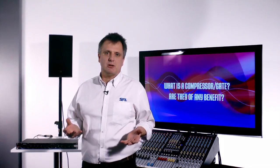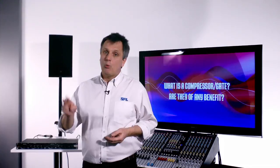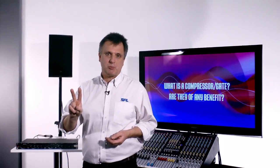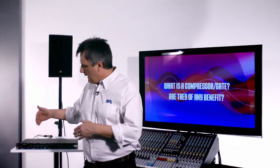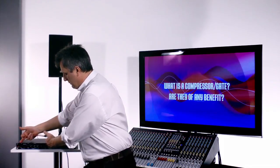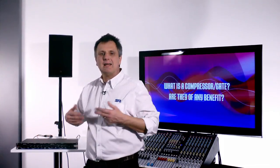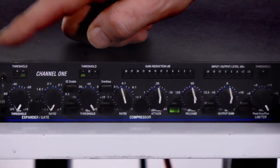A sound engineer will be using this difference, this gain reduction number, to monitor how much compression is taking place. Let me take you through a typical compressor and the controls that we find on it. Now, a lot of these controls, to be honest with you, we can ignore. We're interested in two controls, the ratio and the threshold, and we're interested in one display, gain reduction. So this is a 2-channel compressor. It's a DBX unit. It's quite a common professional compressor, and although it looks complicated at first viewing, the first thing to realise is it's just the repeat of the same knobs. So there are 2 channels here. There's 1 channel on the left and a second and independent channel on the right. So we're going to focus on the controls on the left-hand side.